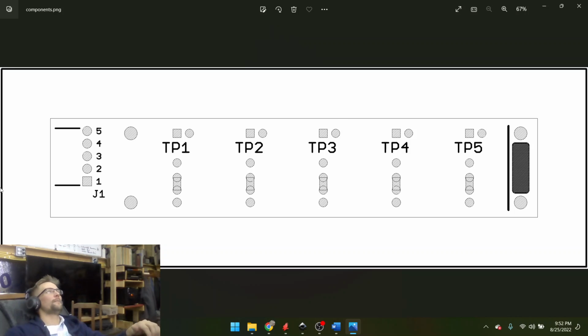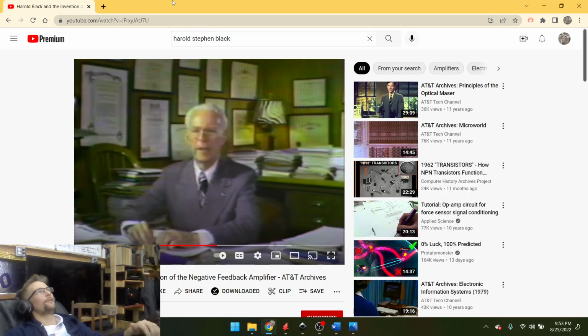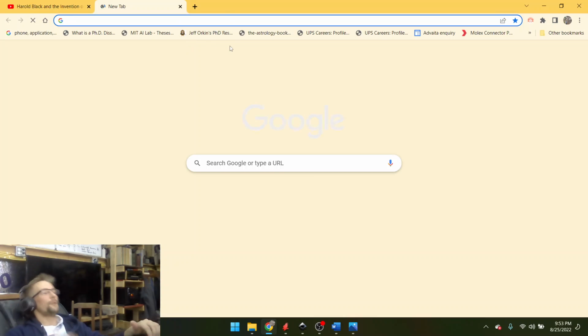And that bitmap layer isn't used in any of the Gerbers, so it's really just there for taking the picture, which I guess is a good reason to call it the bitmap layer. So now how do I get it? Eagle, this version, I'm not familiar with a good way to mirror the layout.